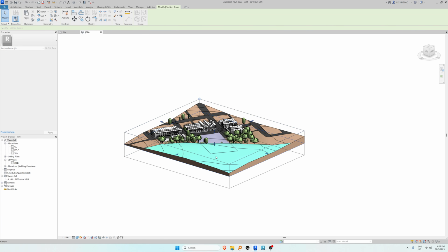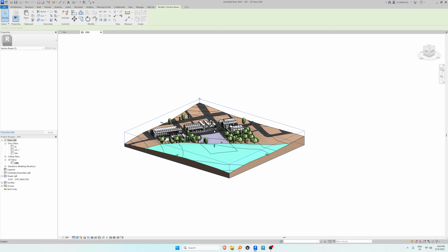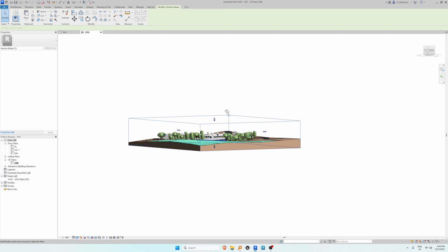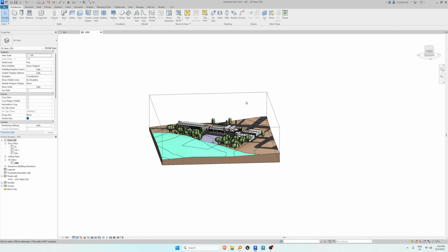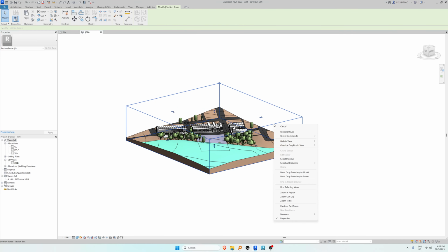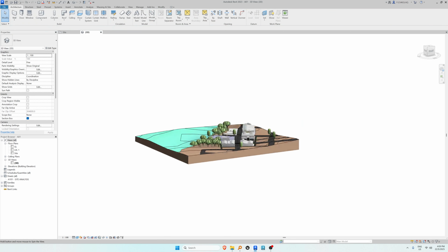If you move the base, it will make this thicker. If you move the base here, it will make it something like this. Okay, you just see how deep you think your one should be, or how tall. But make it a bit tall, because later when we make the diagrams we will need the box to be tall. Okay, once you're done and happy with what you have, you just select the box, right click, hide in view, elements. So you will have this.